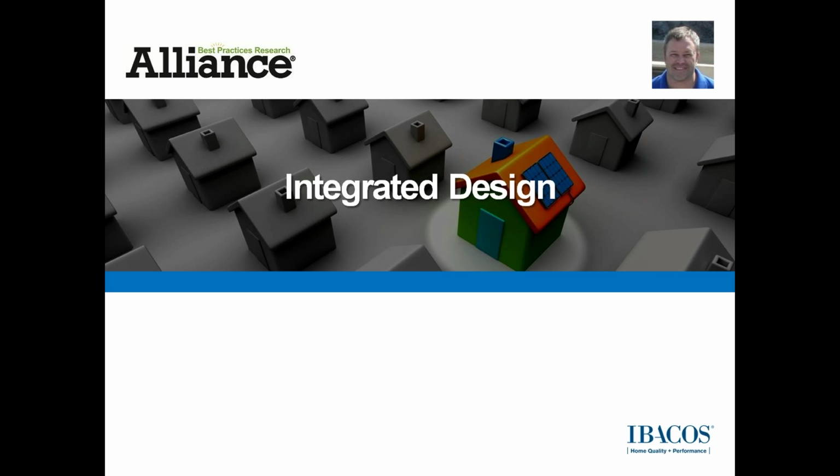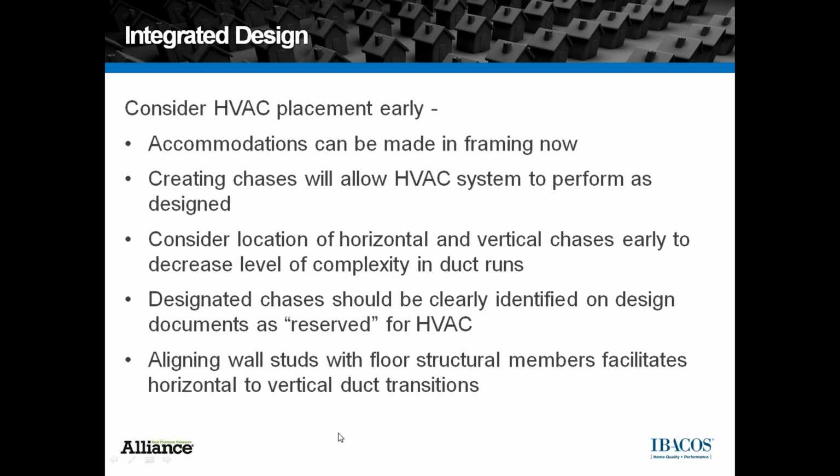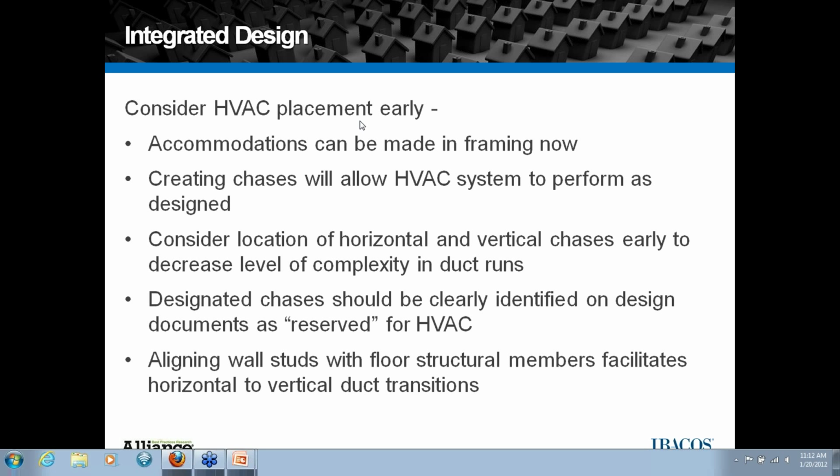Integrated design. Now this is very early in the procedures, long before you've put nail to wood or anything. If you can give consideration to the HVAC placement early in the procedure, early like in the schematic phase of designing your house, you can make accommodations in the framing. You can create a space for that HVAC system to be located and get the performance from the system you need.